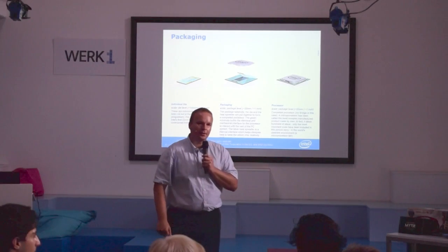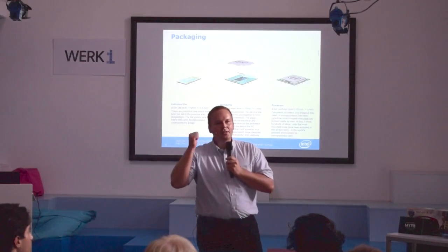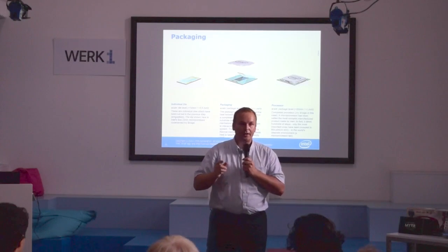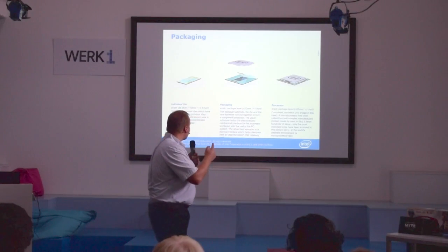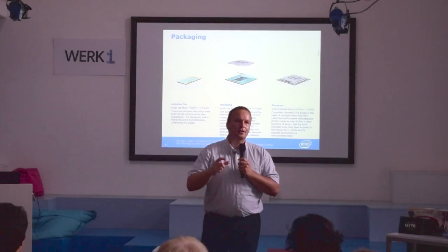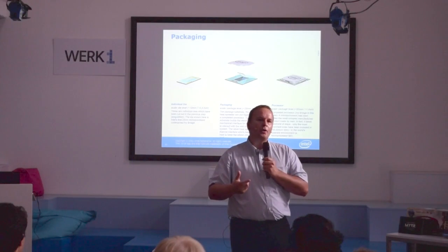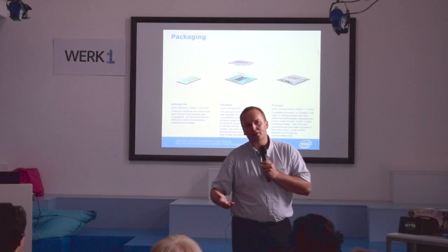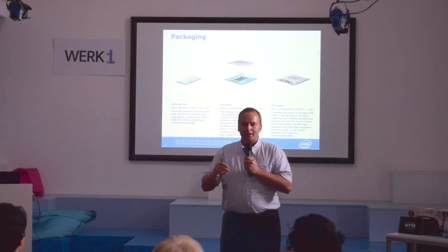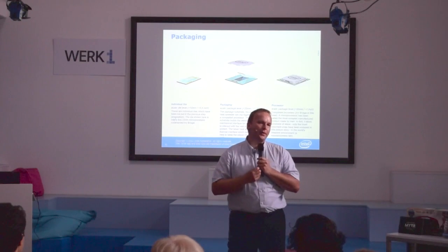And there's another one. Do they either work or not work, or are there performance differences? In this step, it's mostly checked for does it work or does it not work. But then, maybe it's showing on the next slide, there is a so-called process step that is called speed binning, where more tests are applied to the product in order to say, okay, what are the characteristics of this individual die and how fast can it run?